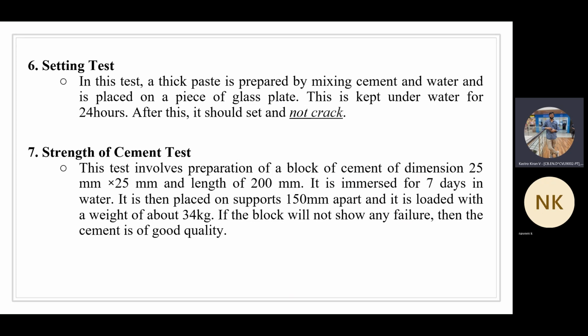Once the 7 days are completed, you are going to place the sample on the supports. And remember, the distance between the two supports is 150 mm. Okay, it should be 150 mm.